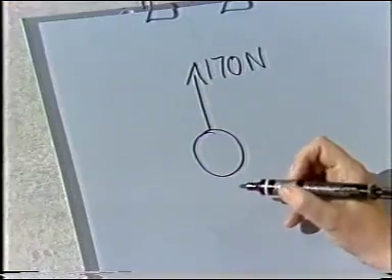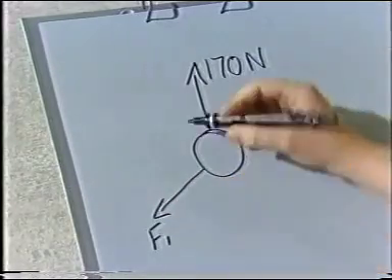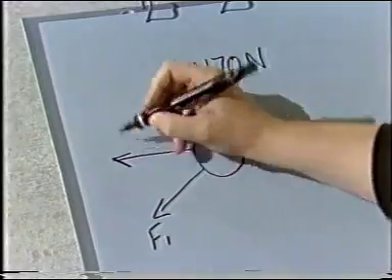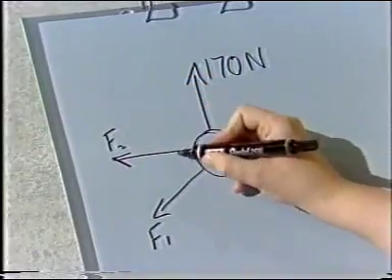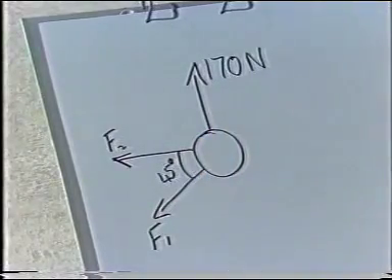Each of the members has a force acting within it, which may be a compression force or a tension force. I'll assume that they're all going to be tension forces, and I'll let the mathematics take care of it if they're actually going to be compression forces. For tension in the members, the pin forces are like this: F1 acting down there, and F2 acting horizontally there. I can apply equilibrium conditions to this free body diagram and find these forces. Working through a structure pin by pin like this is known as the method of joints.